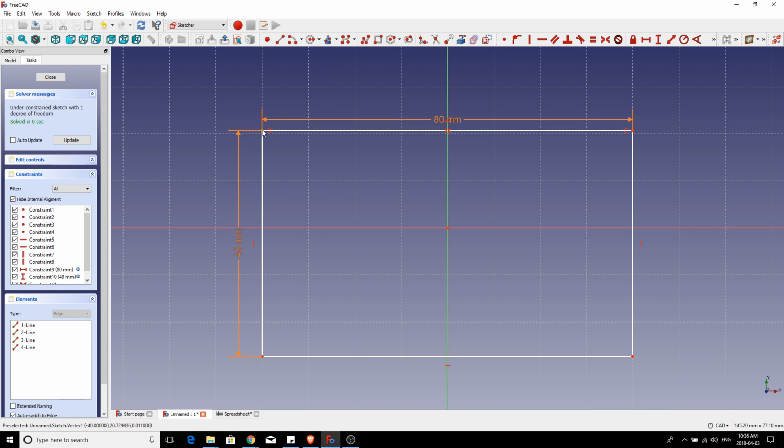And we do it the exact same way. So we're going to click this point. Going to click the bottom point down here. Going to click the axis right here. And we actually can click the exact same button for symmetry, because symmetry is not like the other constraints where we have to specify horizontal or vertical. Symmetry is just symmetry, and it's based on the order that we have clicked on the points and the axis we have selected. So let's hit that symmetry, and we should see it line up vertically as well.